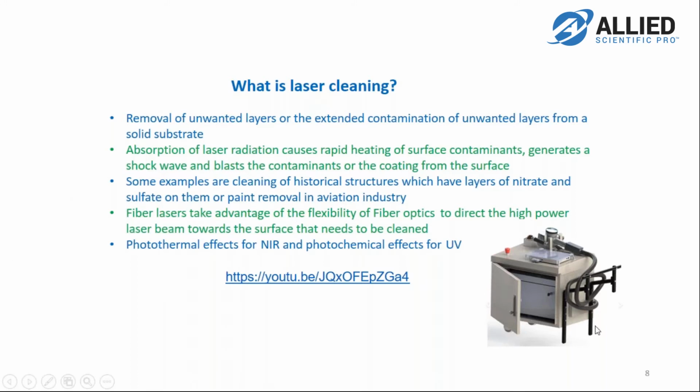You can see this box has all the laser engine, the pumping mechanism, and then there's a fiber optic cable. This is an isolator, which would not allow the radiation to be reflected back into the medium. And there's a galvo and a lens, which has a particular focal length. So you have to focus that on the material that you want to clean.